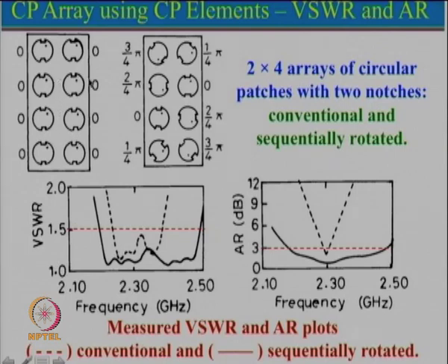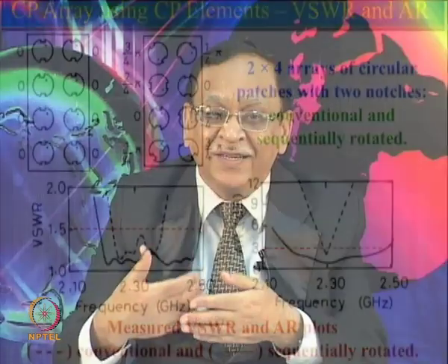But over here, instead of 8 elements which are fed in the same phase, all of these are rotated. So, the concept over here is that instead of using 2 patches, where we had seen 0 degree, 90 degree, for 4 patches we saw 0 degree, 90, 180, 270 and 360. Now if there are 8 patches, what do you do? You divide 360 by 8.